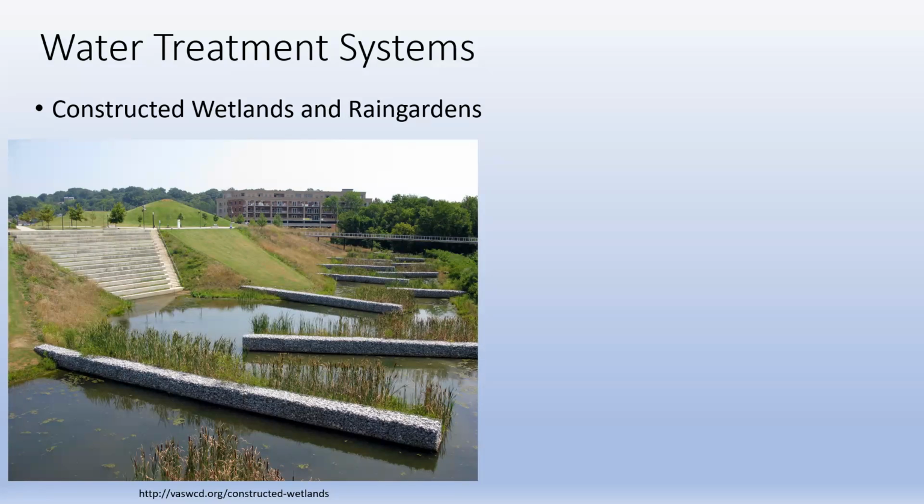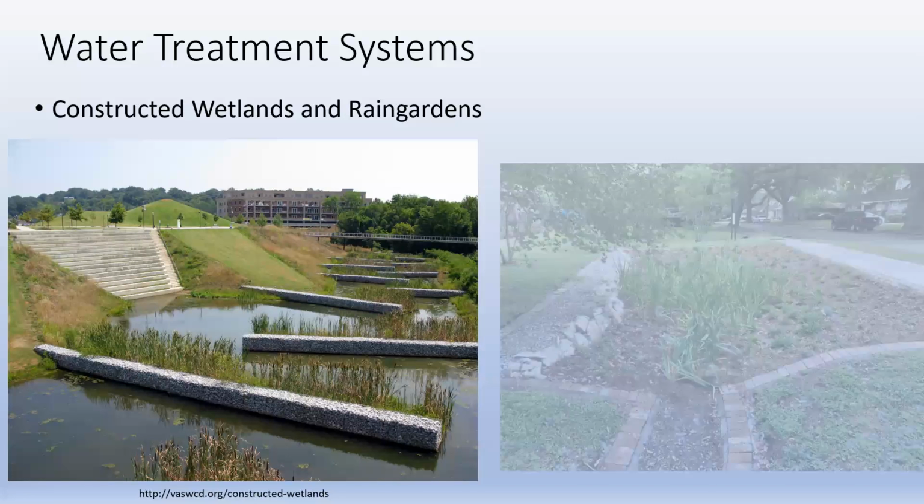you're good to go. From a management perspective, it doesn't end there though, because that plant material should be harvested and removed. Because what's going to happen when that plant material decomposes? It's just going to release all that nitrogen and phosphorus back down the water. So constructed wetlands, great system in certain ways, but there is some management considerations and routine maintenance that are going to go into that.